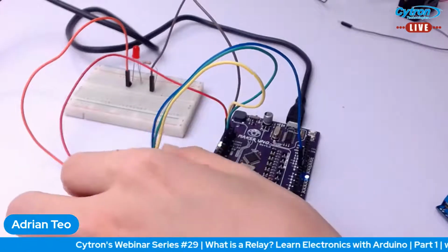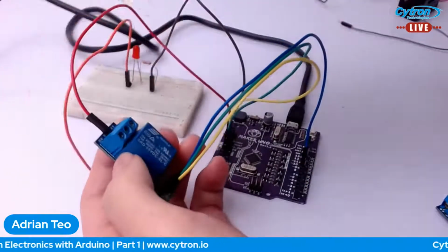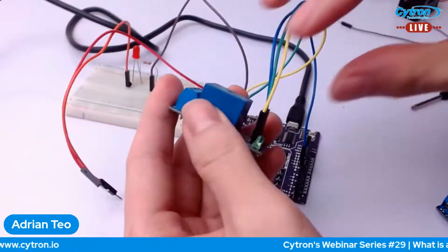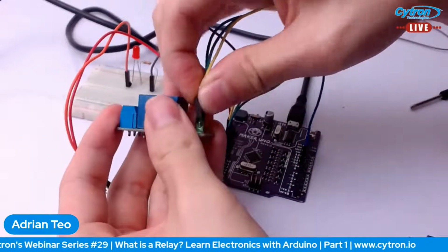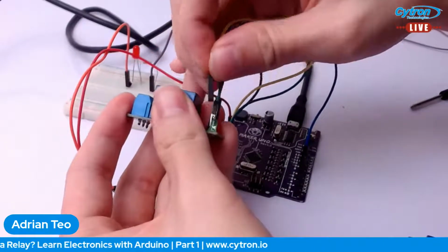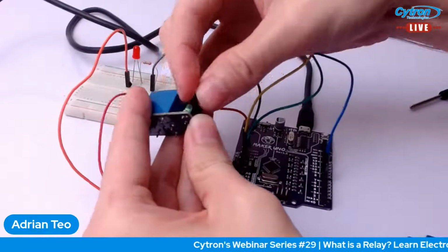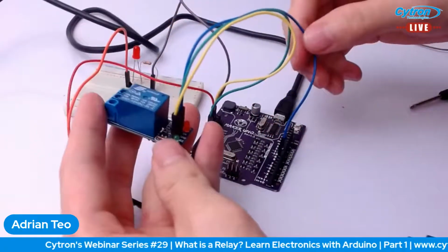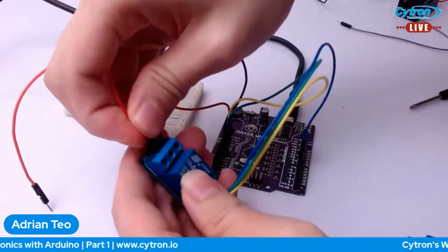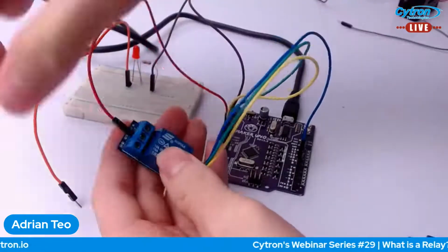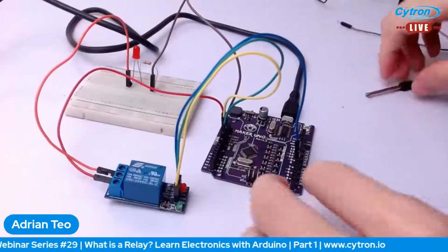Yes, this is a normally open, and I connected it normally open at the beginning. So let's try a different relay. My power should be correct. VCC, ground, and input. Okay, I'm switching a different relay right now. Green to ground, blue to in, correct. 3 volt. Okay, normally open, and O. Okay, this is normally closed. Turn on the power.